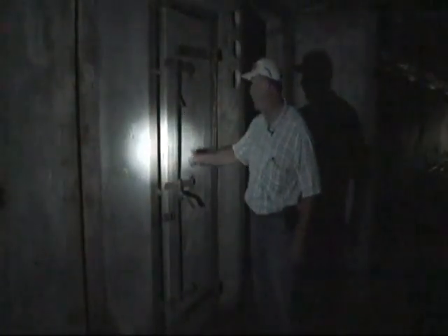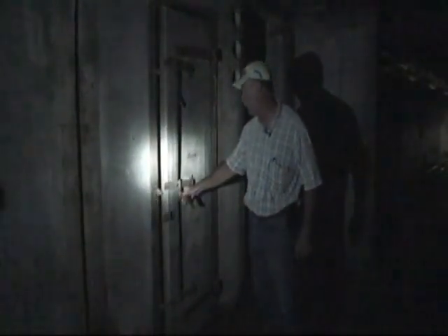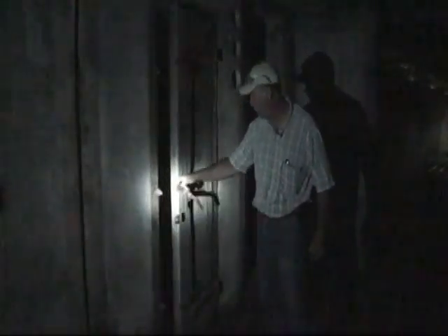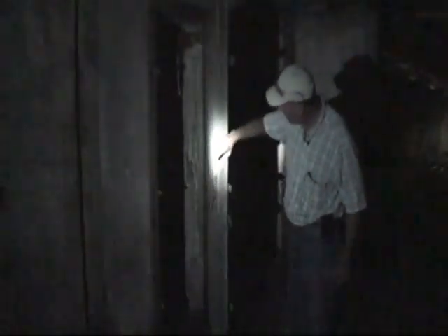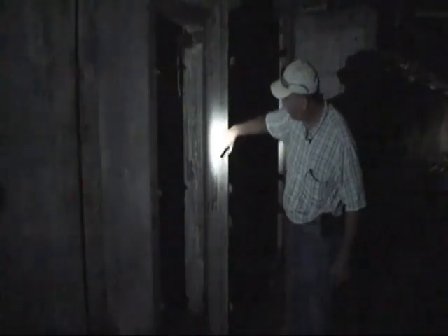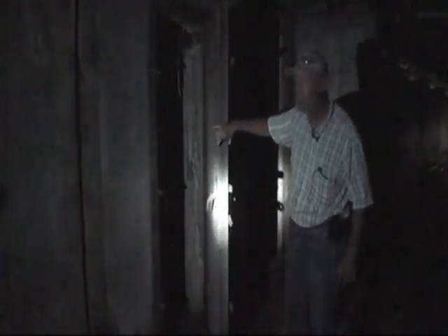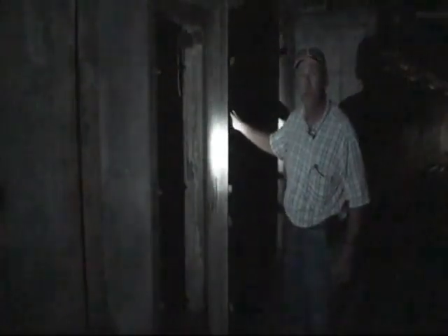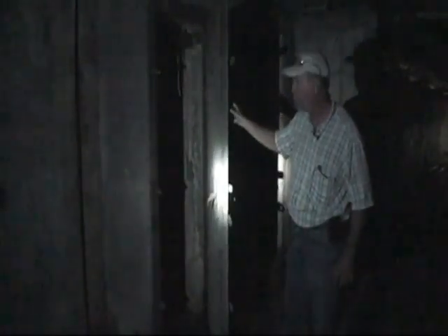Here's an example of a fire door. These are not at all uncommon in institutional buildings, bank buildings, schools and whatnot. It's metal jacketed on the outside. They're real heavy duty. On the inside of this, there will be an asbestos material. Typically it's a thick layer of transite. These doors are considered a non-regulated, non-friable asbestos-containing material, provided proper work practices are used.